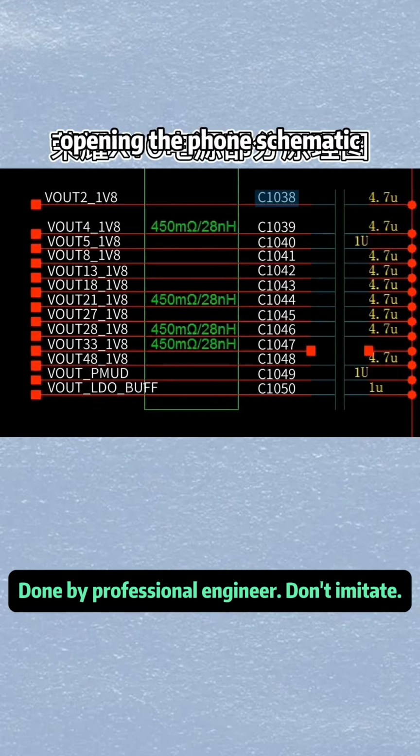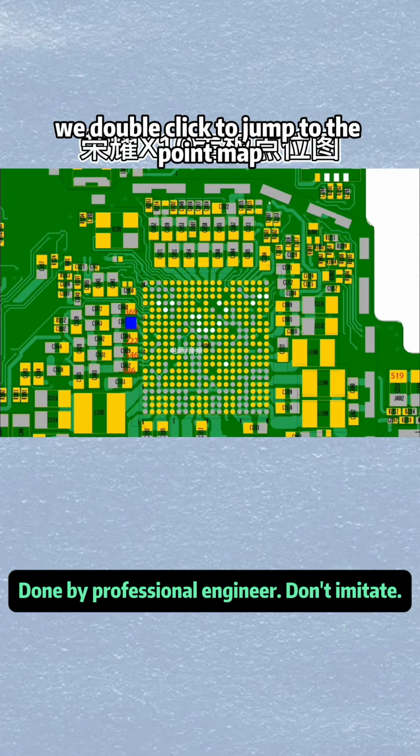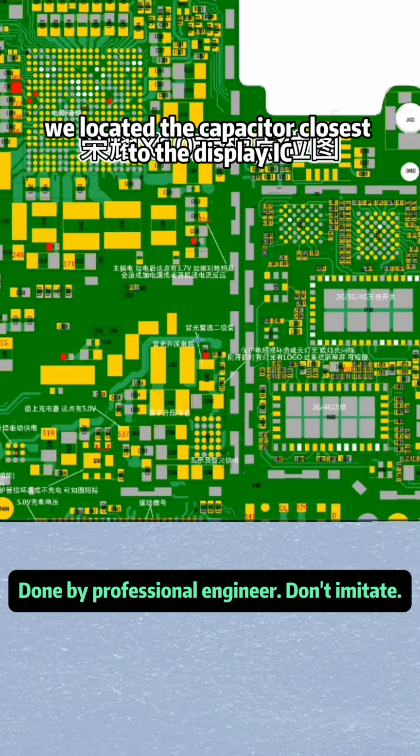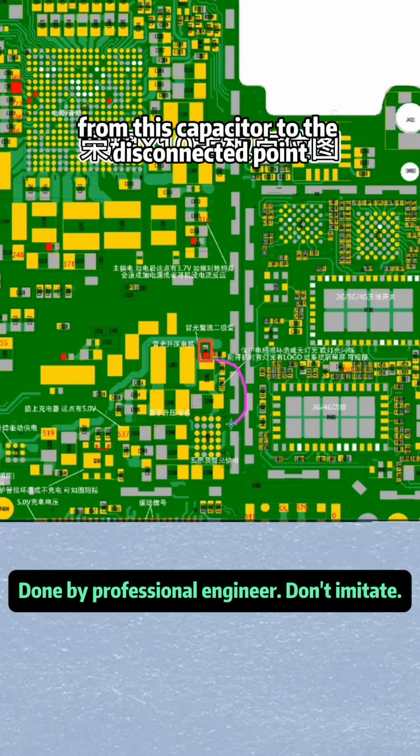Opening the phone schematic, we found a 1.8V power path in the power section. We double-clicked to jump to the point map. All the red-marked areas are part of this 1.8V path. We located the capacitor closest to the display IC and connected a jumper from this capacitor to the disconnected point.